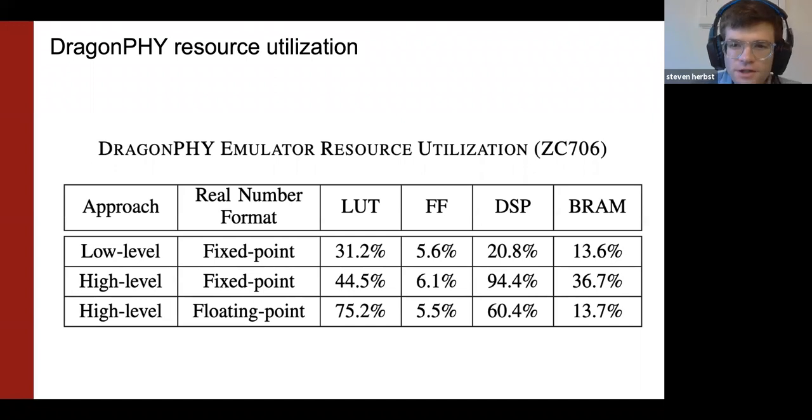And I think there's actually kind of an interesting trade-off there as well, because what I found in some of my work on commercial applications is that the digital parts of the design, in other words, stuff that we're not changing, that we're just trying to pull into the emulator, mostly consumes LUTs. So if the analog models can kind of stay out of the way of that, that's good, because it improves the chances of being able to fit the design onto the FPGA. So it is a nice feature that, if the analog models mostly consume DSP blocks and the digital parts of the design mostly consume LUTs, they're at least not fighting for the same resource.